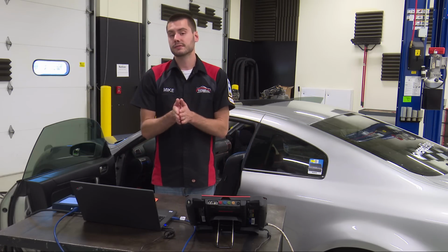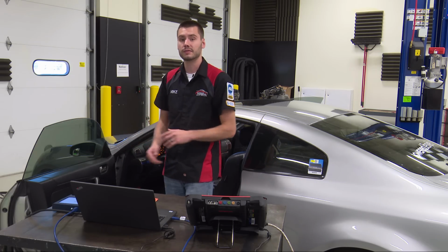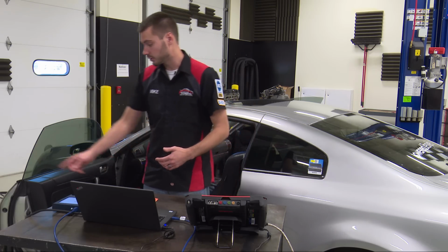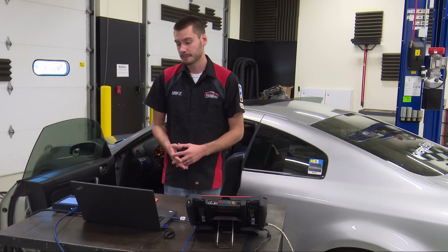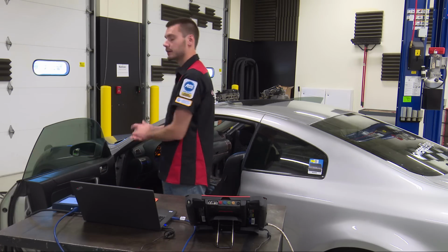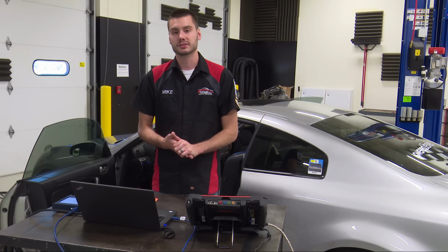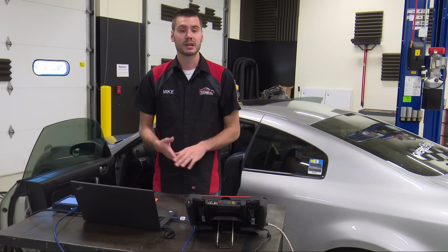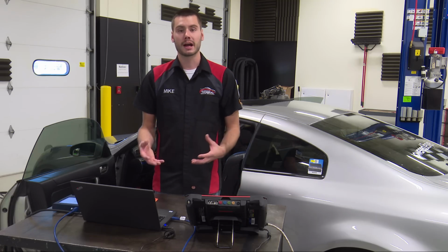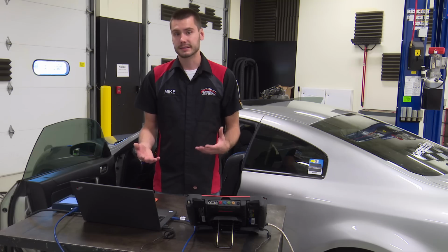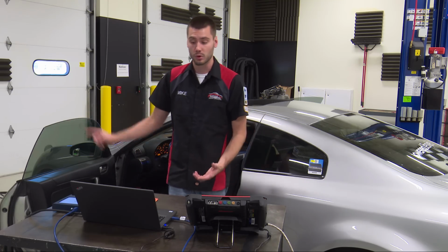Now, if you're noticing very slight differences, you have to remember that there could be wear components in the regulator assembly of the window, in the tracks on the sides. Typically, from a comparative process here, we usually see the driver's side working a little bit harder than the passenger side because there could be things wearing out, getting sticky, getting gummed up. The regulator might be a little bit dry. It might not be as lubed up as the passenger side. Typically, the driver's side does have to work a little bit harder because it gets used a lot more.